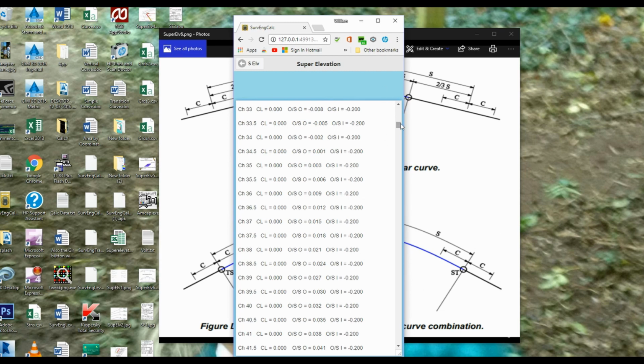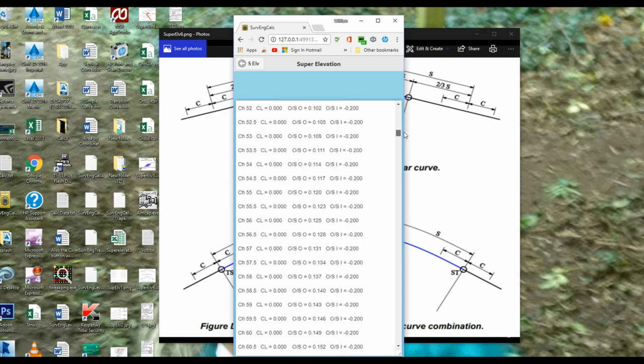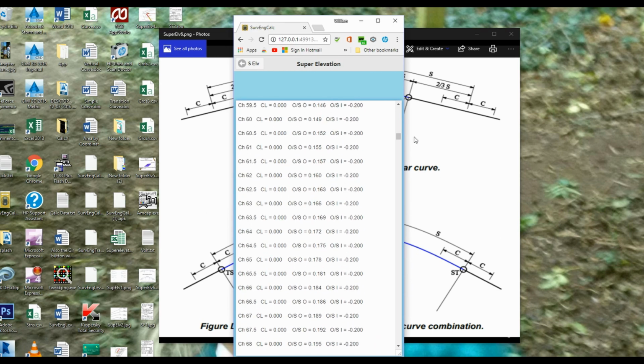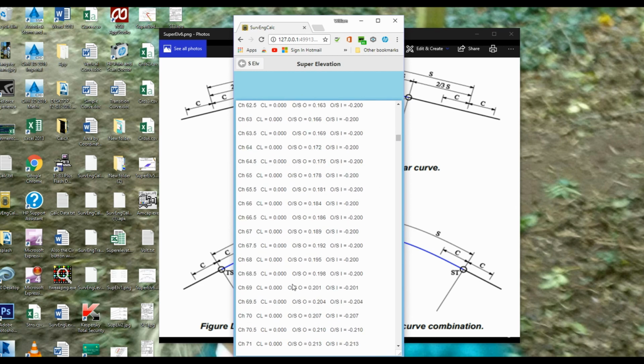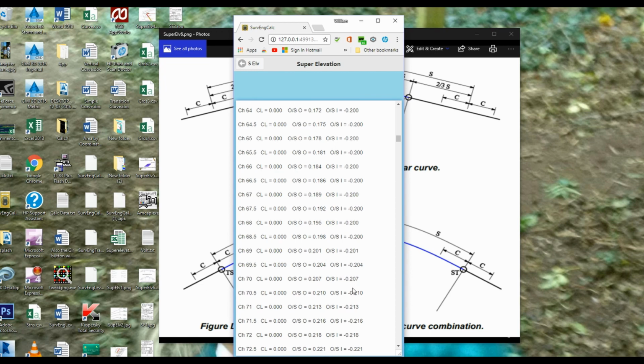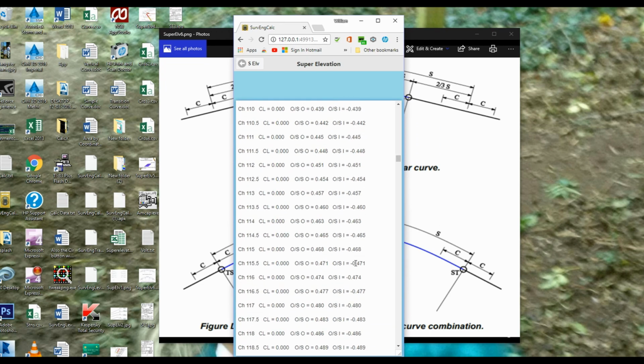Then we're going to look for continuous crown, which should be twice 34.412, so it should be 68.824. There we go, 68.5. So near enough 69 meters there. So there we go. We've got a continual crown there. So that's our levels there. Offset in, offset out, continuous crown. And then it should be all the way up to full super elevation.